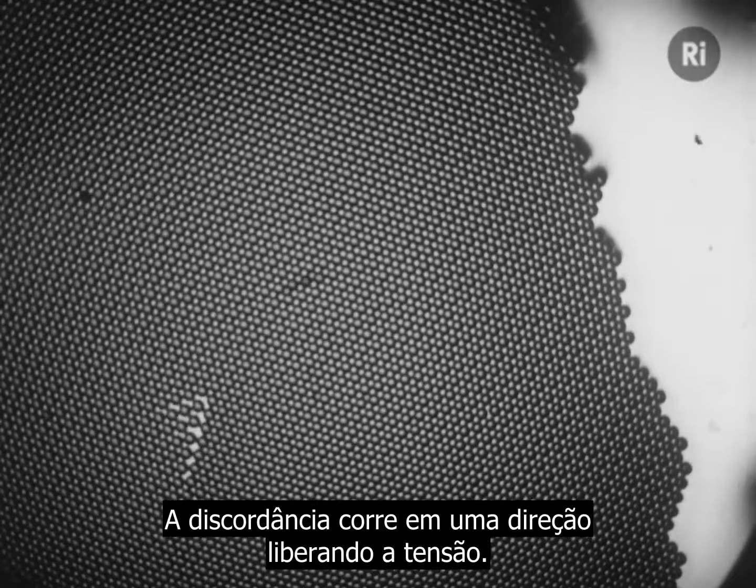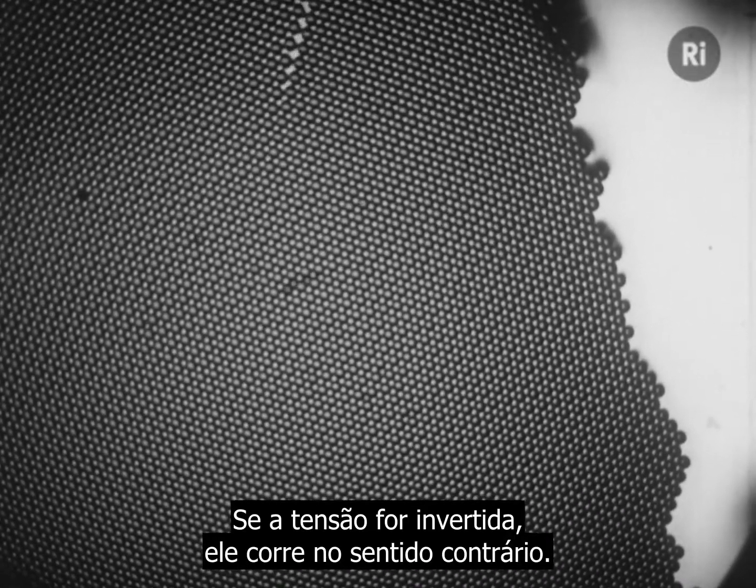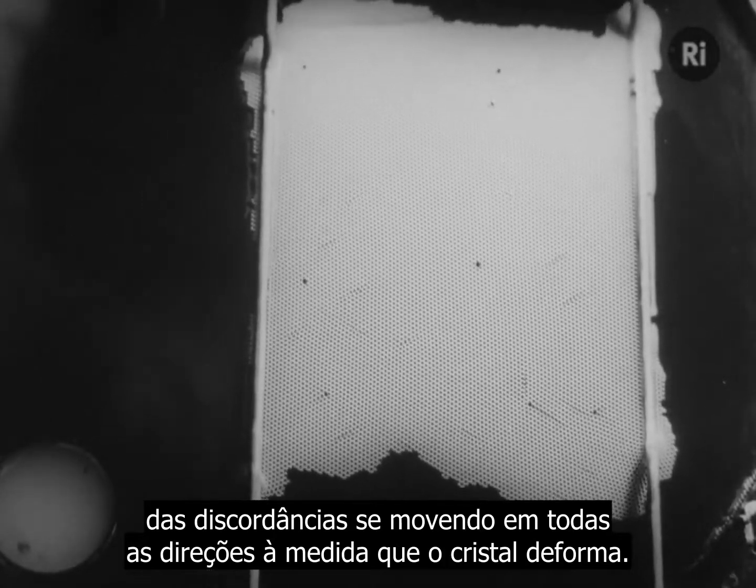The dislocation runs in a direction which relieves the strain. If the strain is reversed, it runs the other way. After it's passed, the crystal is perfect as before. Now that we've seen what a dislocation is, we can look again at the picture of dislocations moving in all directions as the crystal is deformed.